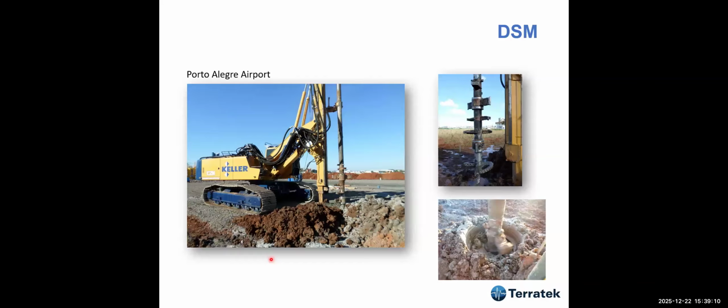And this is the project I did with Keller, and they were the contractors, and they brought a very interesting tool to carry out the mix, and this is how it worked. So the jets do not go out, they go in. So they just mix. The diameter is given by these two, and the diameter was about 9 centimeters.